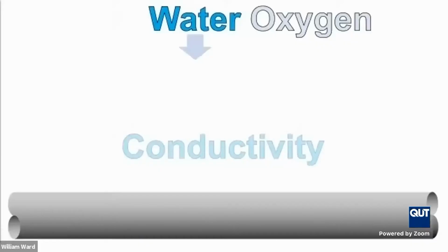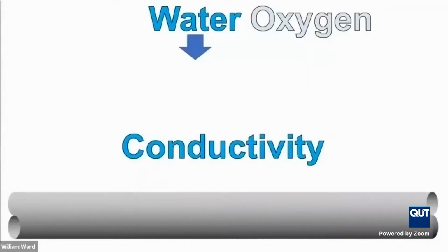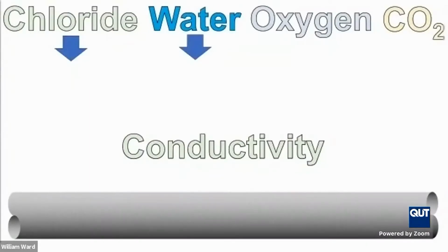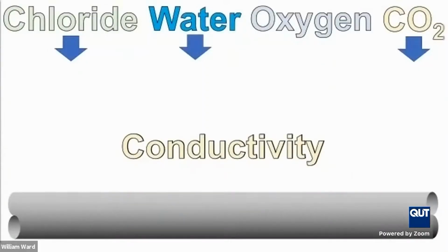which may be appropriate. We could also measure conductivity, which captures the presence of water, presence of chloride, because that'll make a more conductive concrete as well, presence of carbon dioxide, again, increasing the conductivity. This is one way we can evaluate. It's a little bit unsophisticated, but it does catch if that concrete environment is going to promote corrosion.